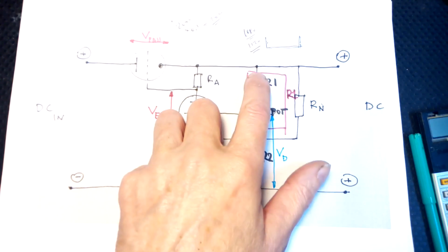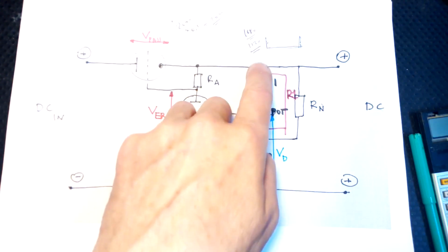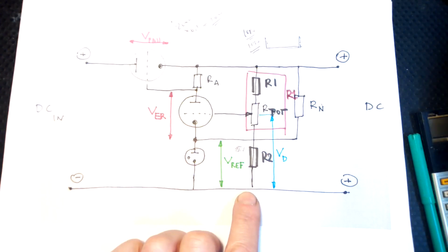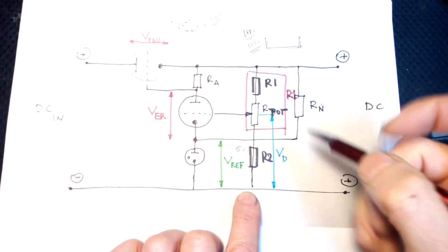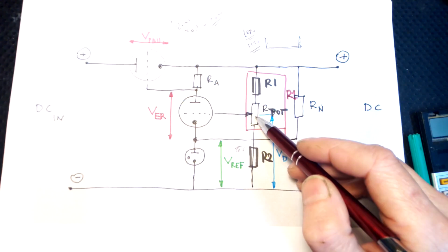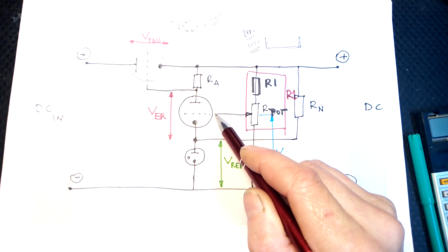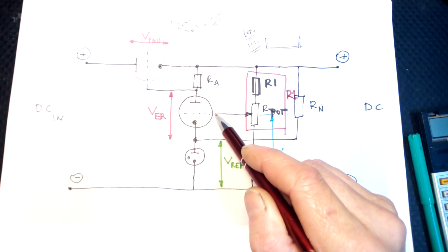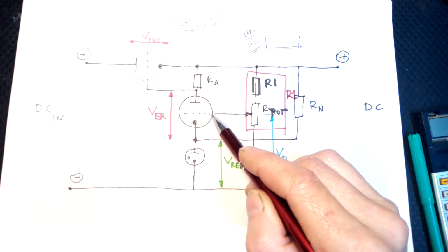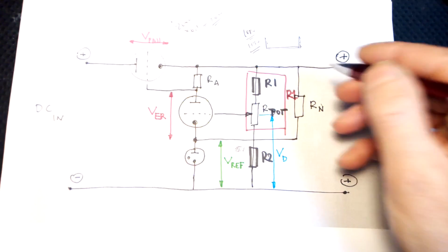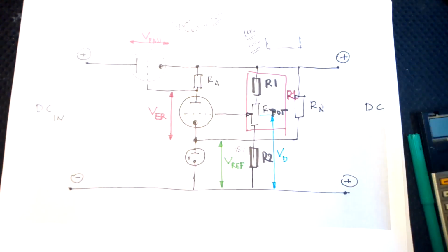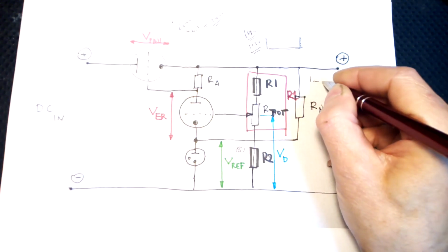So we have to try to minimize the current in the voltage divider, especially since we don't need any current here. It should be no current. This is just potential here, error amplifier. So let's say we want to run it at 1 milliamp.